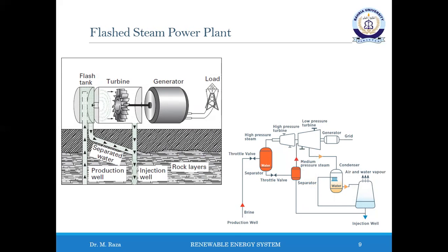To deal with hot high pressure water requires complex equipment designed to reduce the pressure in a controllable manner and induce flashing. Again, a conventional condensing steam turbine is at the heart of the plant, but lower steam pressure and temperature of about 0.5 to 0.6 megapascal and 155 to 165 degrees Celsius are common. So the plant typically requires more steam per kilowatt hour than would be required in a dry steam plant, say around 8 kilogram per kilowatt hour.